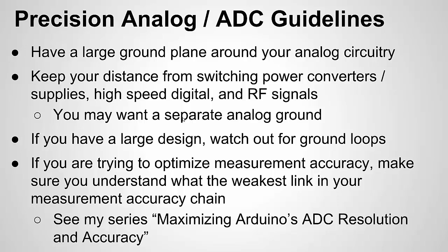The problem though is, if you think VCC is 3.3 volts, but let's say the regulator you're using is actually putting out 3.27 volts, that means every measurement you're going to make is going to be 30 millivolts off, because you're not working with an accurate reference.